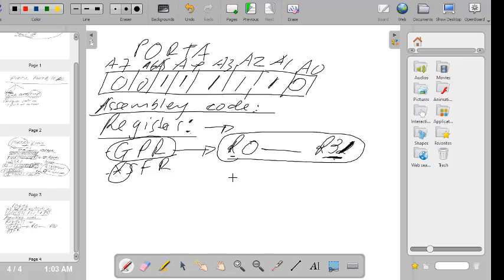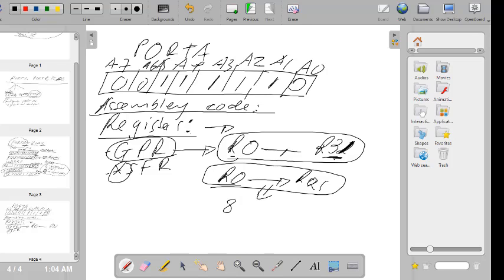But right now, I want to show you that the registers from R0 to about R25 are 8-bit registers, meaning that these registers can only hold 8 bits of information. And then from R26 to R31, these registers are called the XYZ registers.